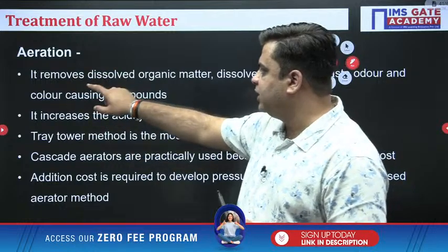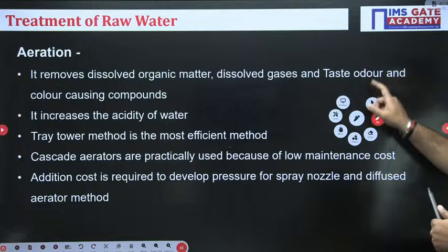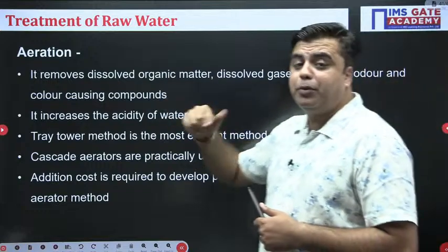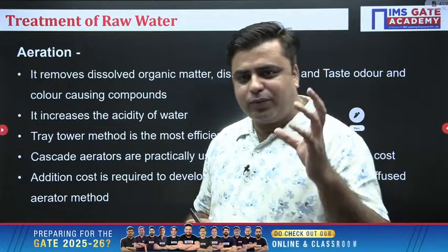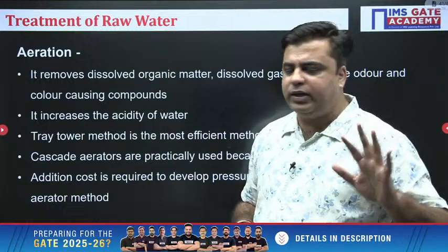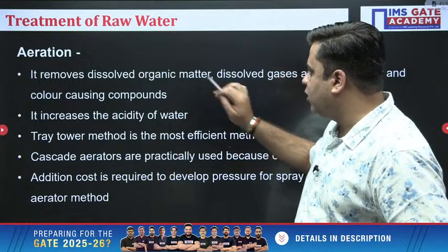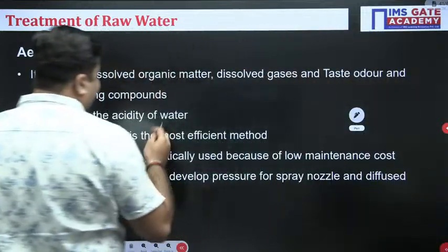So I have listed this down. It removes dissolved organic matter, dissolved gases, taste and odor, and color causing compounds. Basically aeration removes the majority of the dissolved impurities, specifically dissolved organic matter, dissolved gases, taste and odor, and color causing compounds like iron and manganese.